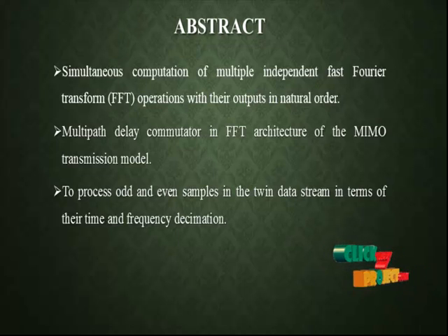These fast Fourier transform operations are carried out by an FFT processor that can handle simultaneous computation of multiple independent data streams and provide the output in terms of their natural orders. In our product, we have designed a multipath delay commutator in the FFT processor for the MIMO transmission model. The odd and even samples of the twin data streams are processed in terms of their time and frequency decimation